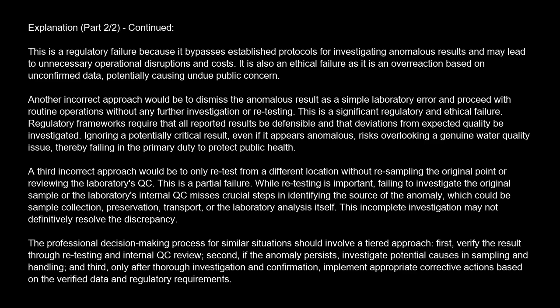Regulatory frameworks require that all reported results be defensible and that deviations from expected quality be investigated. Ignoring a potentially critical result, even if it appears anomalous, risks overlooking a genuine water quality issue, thereby failing in the primary duty to protect public health. A third incorrect approach would be to only retest from a different location without resampling the original point or reviewing the laboratory's QC. This is a partial failure.